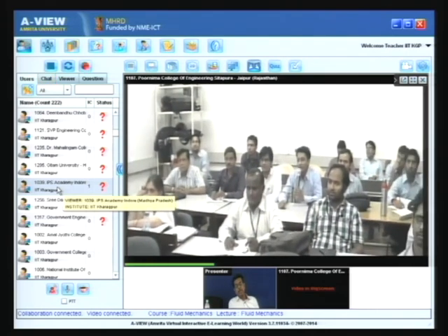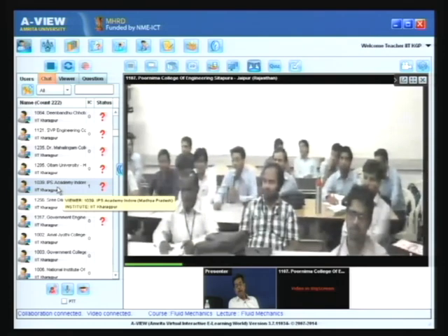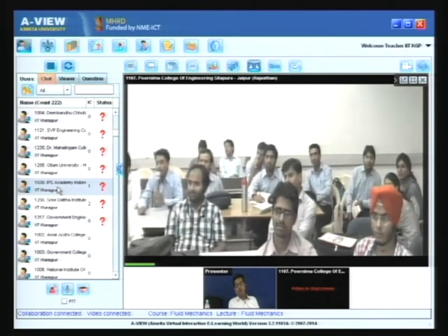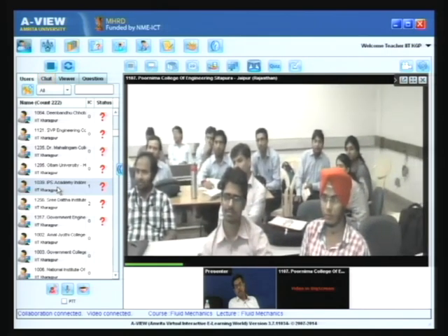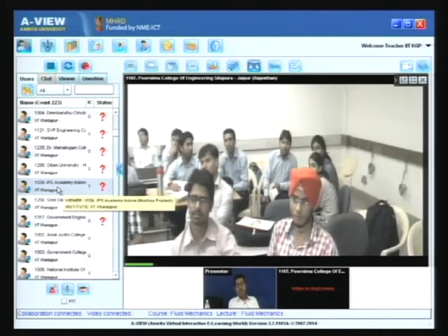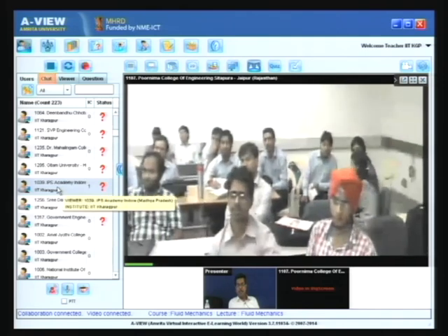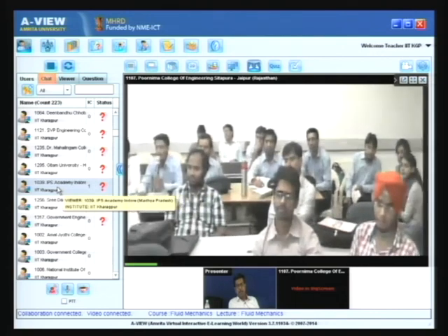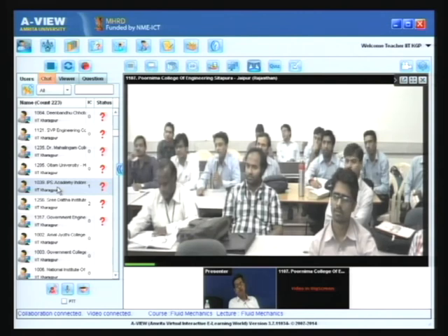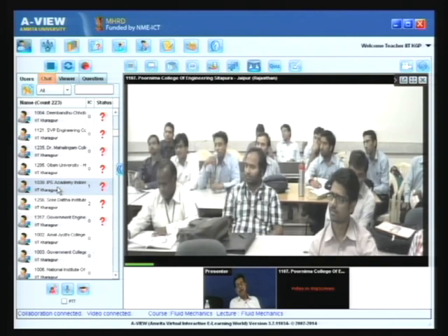First of all, a gross understanding of the creation of lift for the flow of air past an aerofoil can be made by Bernoulli's theorem, no doubt, as you have told, is correct. The design of the aerofoil section is such that the fluid is accelerated on the top and decelerated at the bottom, but this is merely a gross understanding. Many other fluid mechanical phenomena take place when the fluid flows over an aerofoil. There is an expansion wave on the upper side of the aerofoil.